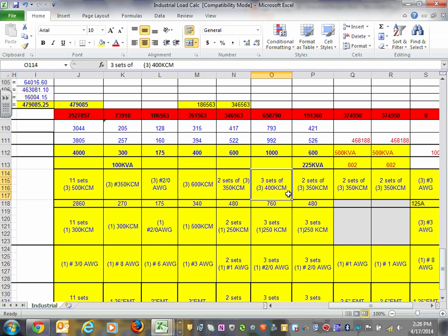But if we are to size it with conductors, or bus ducts, you can have a feeder bus duct that brings all the power, and you feed it directly from a switchgear. I'm sure you guys have seen it.